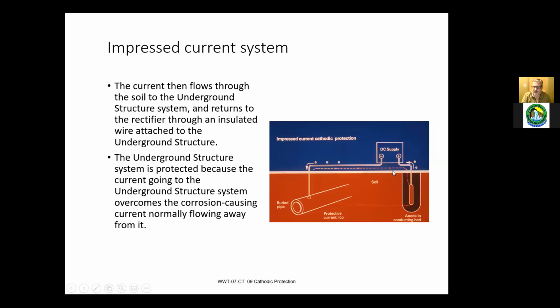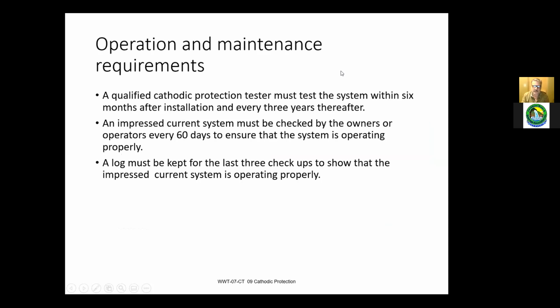So if your rectifier readings are starting to drop off, it means your anode is potentially being reduced in its capacity to absorb. So you need to crank up the rectifier, which basically supplies more DC power down the line to the pipe to force everything towards the anode. So they suggest every 6 months, but we do ours every 60 days. We take a look at it.